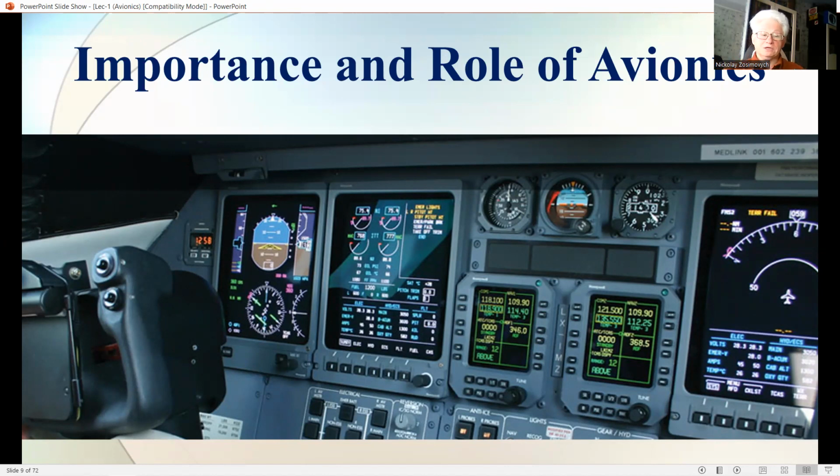These include solid-state rate gyroscopes and accelerometers to measure the angular and linear motion of the aircraft, and air data sensors to measure the high airspeed and incidence. There are also the pilot's control stick and rudder sensor assemblies and electrohydraulic servo actuators to control the angular position of the control surfaces.